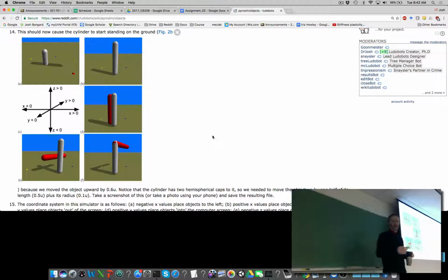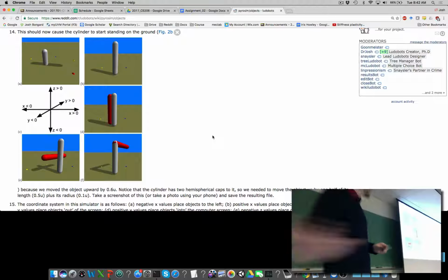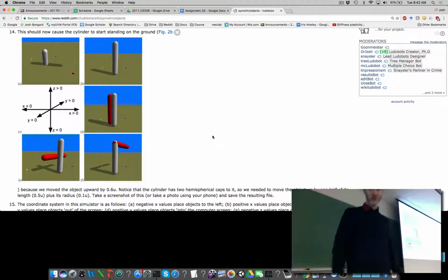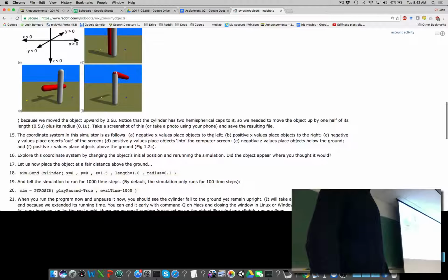So I also want you to get into the habit as you work through here of making predictions about what your robot is going to look like or what your robot is going to do when you make a change to your code. One of the nice things about working with physics engines is you can kind of see everything, right? So this is sort of proactive debugging, right? You'll know that you have a good intuition if you set R1, R2, and R3 to be 1, 0, 0 and you start it up, and if your cylinder does not lie horizontally, you're missing something, right? So feel free to play around with the simulation to build up an intuition for specifying 3D coordinates for your objects.